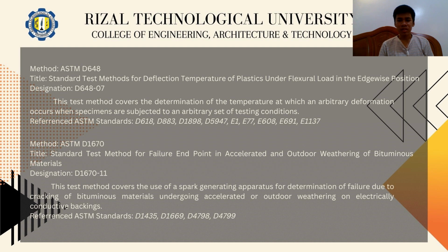Data obtained by this test method shall not be used to predict the behavior of plastic materials at elevated temperature except in applications in which the factors of time, temperature, method of loading, and fiber stress are similar to those specified in this test method. The data are not intended for use in design or predicting endurance at elevated temperatures.